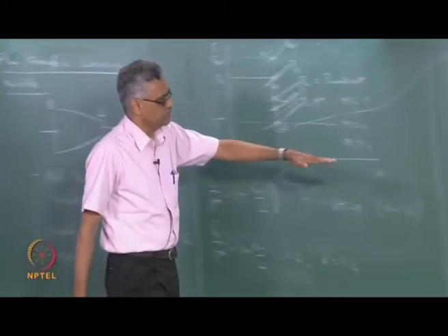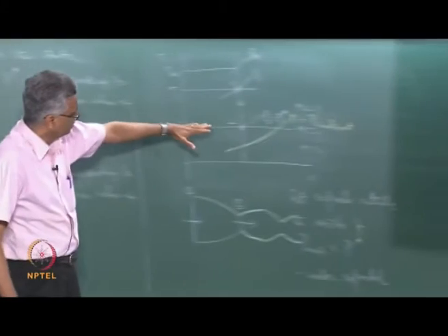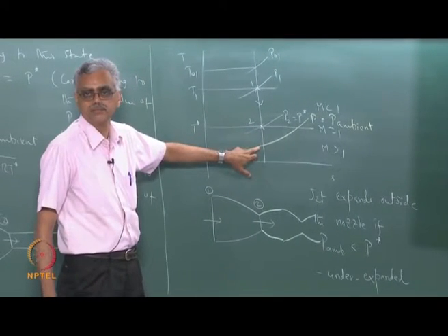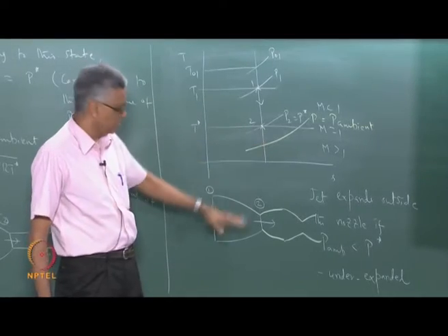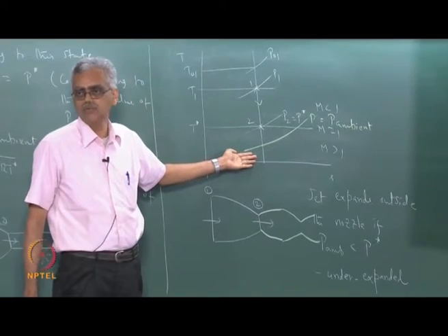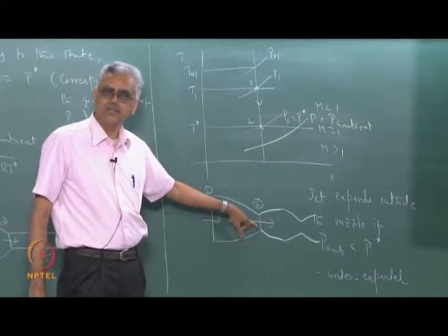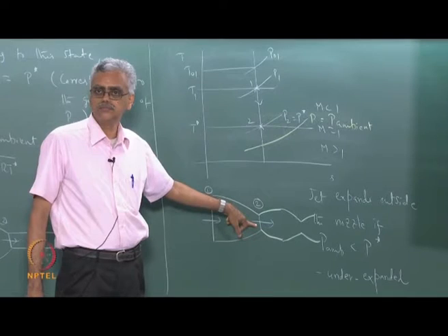See, any further reduction in pressure here, we can argue this in many different ways. Any further reduction in pressure is still not possible because of the conditions that we set from the area velocity relationship. The other physical way of stating this is, if I reduce the pressure some more, the flow at the exit of the nozzle is already traveling with the speed of sound.